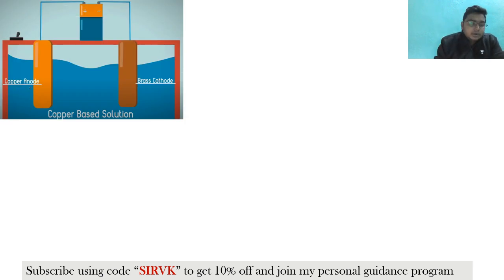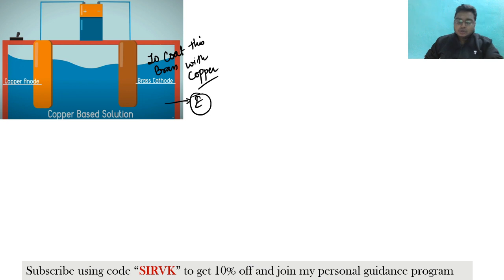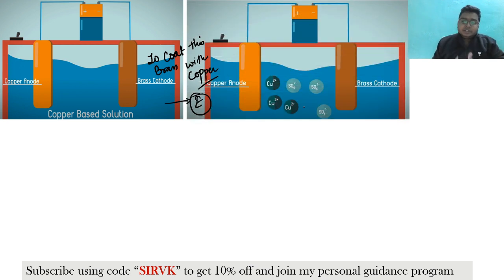Suppose we have taken a copper anode, and this is a brass cathode. My basic intention is to coat this brass with copper, isn't it? That's why we have put this copper electrode. You have dipped them in an electrolyte, and this electrolyte is a copper based solution, basically copper sulfate. In this copper sulfate solution, the copper will get separated, and this is the sulfate. We have seen that this is the positive terminal and this is the negative terminal. So this will be negatively charged, and this will be positively charged, correct?